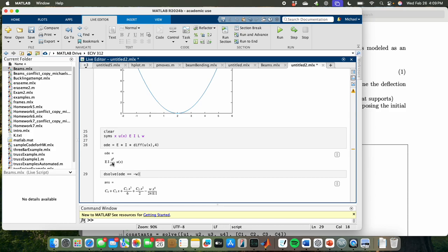If you look at the solution that's on there, it does it 2 different ways. It leaves C1, C2, C3 as separate variables and solves for them using solve commands, or you can apply the boundary conditions. So for a simply supported beam, what are the boundary conditions? Simply supported beam. What's that? Deflections are 0 on either end.